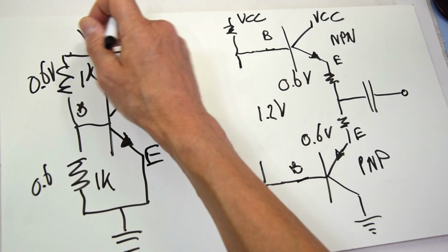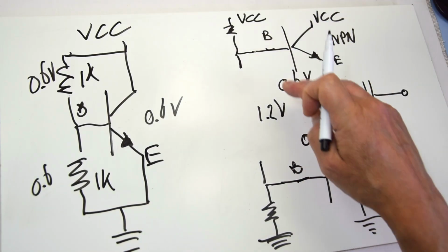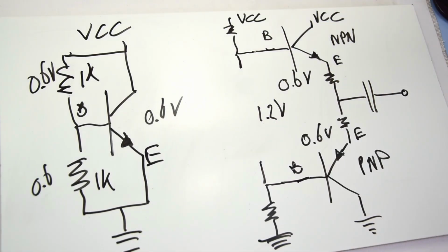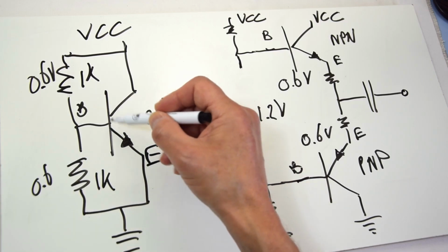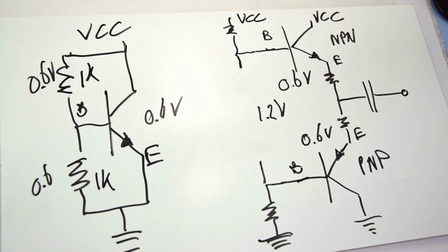In this way we create exactly the voltage drop we need between these two bases, and it has the same temperature characteristics, meaning the voltage drop will go down when the components heat up, because this transistor has similar characteristics as these transistors. Let's see how it looks if I put this on the breadboard.